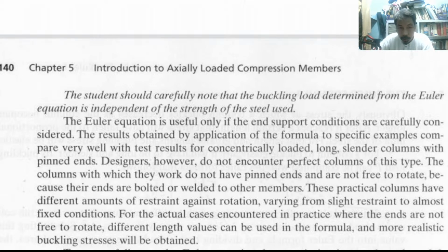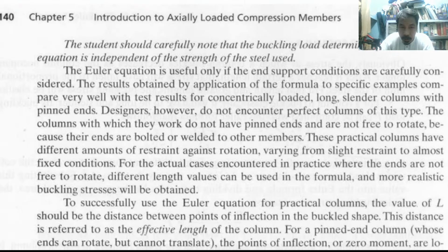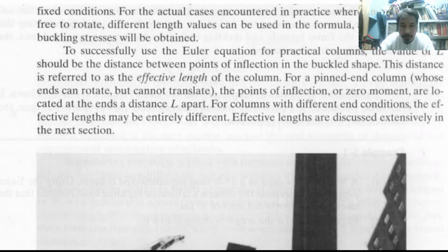To successfully use the Euler equation for practical columns, the value of L should be the distance between the points of inflection. So meaning we need to put in the K factor. Not only the length, but we have to use the effective length.